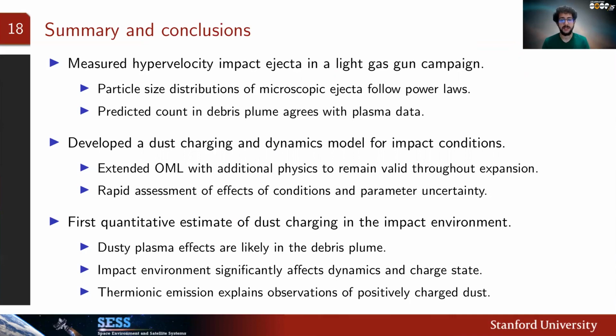I found that dusty plasma effects are likely to occur in the debris plume shortly after impact. I also showed that the impact environment significantly affects debris evolution and that we need to account for the effect of the partial vacuum at AVGR when extrapolating to space-based impacts. I also identified thermionic emission as the most likely mechanism for observations of positively charged dust in impact experiments. And this is a first step towards understanding how dusty plasma effects and hypervelocity impacts affect the threat to spacecraft electronics posed by the impact plasma.